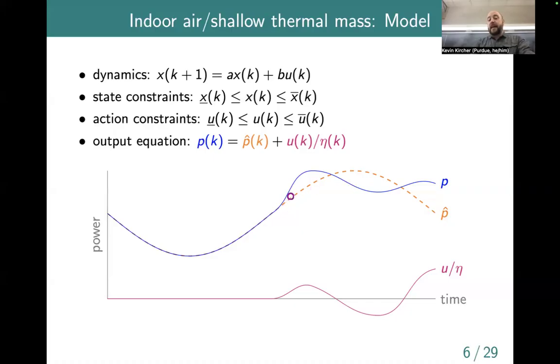So the idea that I had when making this was that we'd be pre-cooling the building, say from noon to 2 p.m., something like that. And then bringing the temperature down, not super cold, but colder than normal. And then during the late afternoon when it really gets hot, we use some of that stored cooling from the capacity of the building in order to reduce the power consumption. And then there might be a recovery period after. So we might actually let the building get hotter than usual, and we might need more power to bring it back down to its normal state.